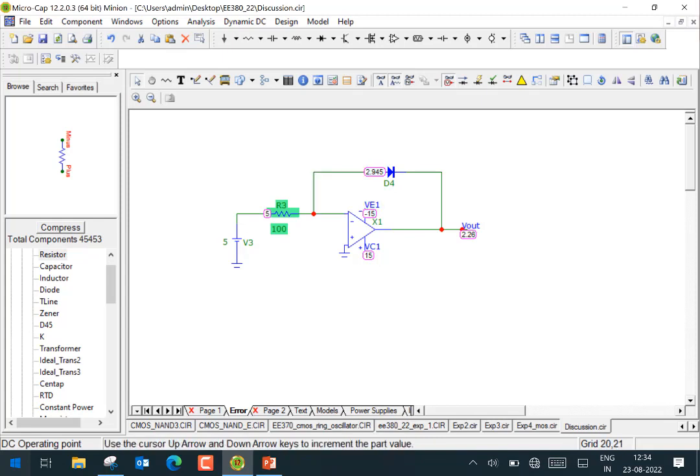The current that can flow in the op-amp here, eventually the current comes here and goes into it, is a maximum of 25. So imagine now the maximum current that can flow is 25. If you have 5 minus 25 milliamperes multiplied by this, you'll get obviously some positive voltage here. So it's not working properly because you're violating the current limit. And you can see here, if I just double click on this and change it, it works fine now.